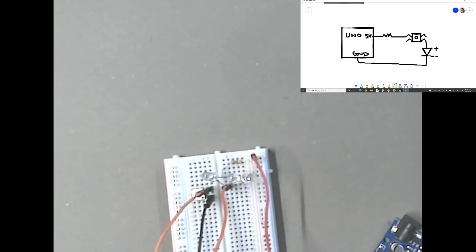All right? It's similar to what we've done before in the video, but you're putting the button in a different place. So the thing to double check to make sure that you did your circuit correctly is right here, guys. I'm going to highlight in yellow. See the resistor? The resistor is connected to the button. All right. So before you try it, just make sure that you got a resistor that's connected to the button.